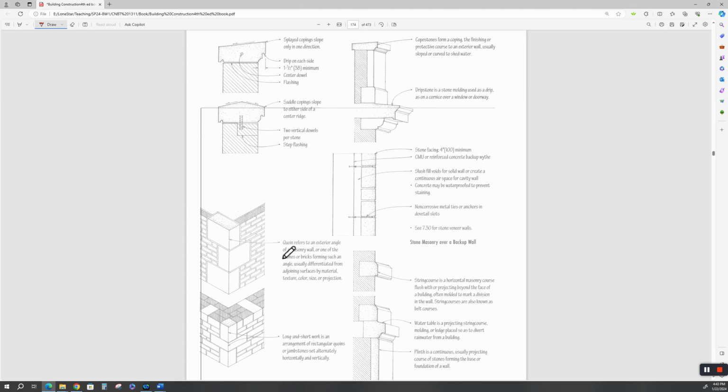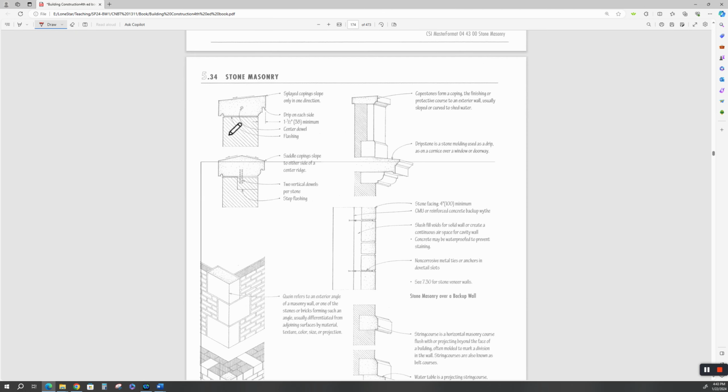And we'll get to these definitions in a minute. But how do you cap off traditional stone masonry? Well, this is a capstone. It's splayed copings. It's called a coping. I call it capstone, but well, this is a traditional capstone. Okay, all right, whatever. Splayed copings are also a capstone. They cap off the wall, just like that flashing on that CMU wall. That's a cap flashing, like a cap on your head. All right. It's just real simple.